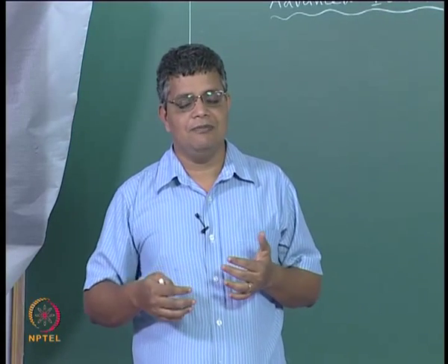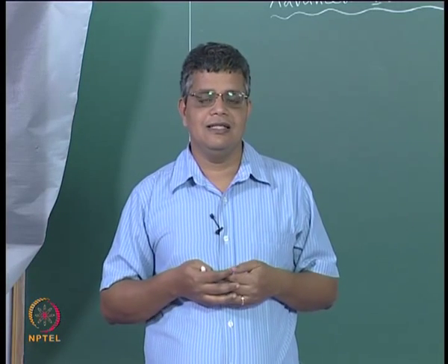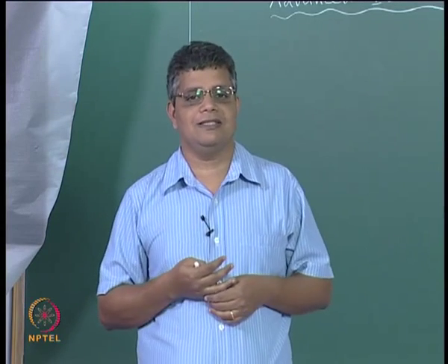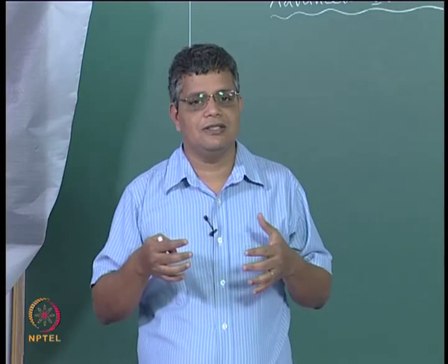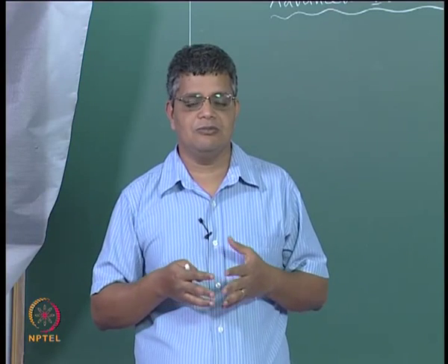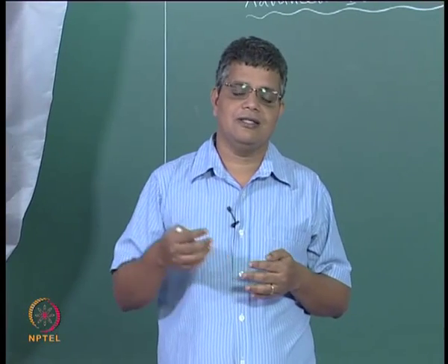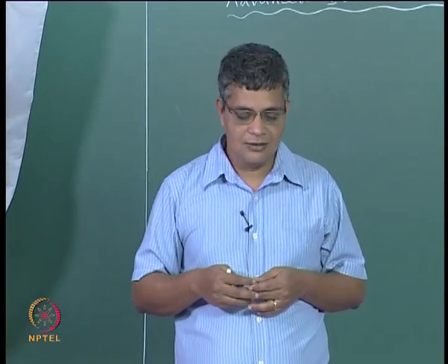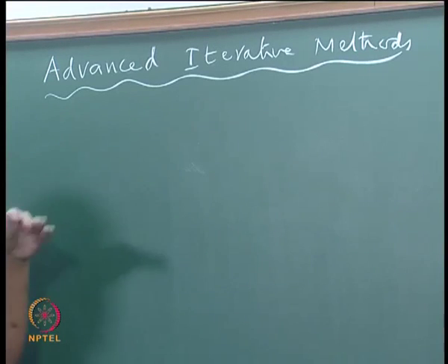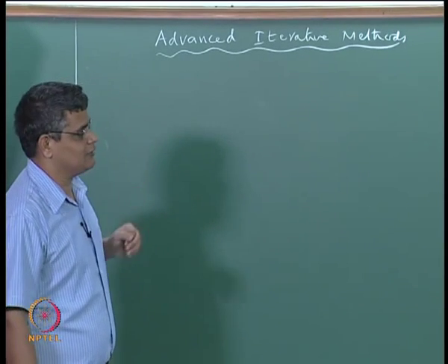So if we can make some calculations and get at an improved solution, then we can update the values in the coefficient matrix itself. So it is in that sense, for a CFD problem, iterative methods are the most suitable methods when we are looking at an overall solution for a 3-dimensional or a 2-dimensional case. So that is why we want to use iterative methods, which allow us to improve upon the coefficients in the coefficient matrix A corresponding to each discretized equation.